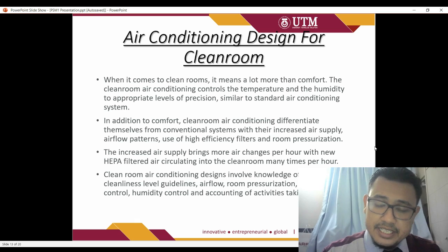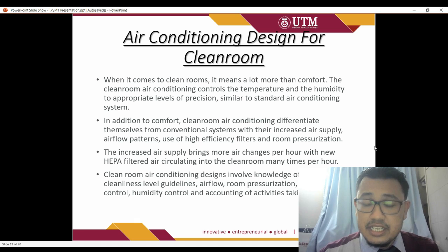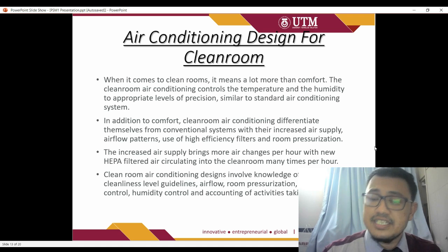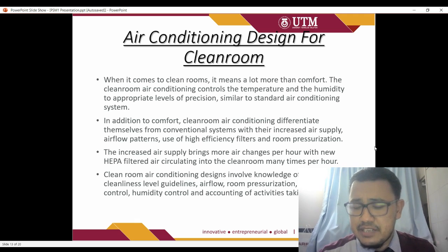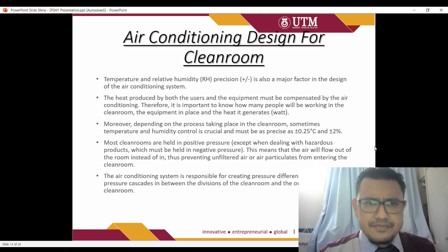We can follow the table: 80 air changes, 100 air changes, 60 air changes based on the clean room class. Then clean room air conditioning design involves knowledge of the regulations, the guidelines, the airflow, room pressurization, temperature control, humidity control, and accounting for the activity taking place inside, for example in the electronic, pharmaceutical or food industry.